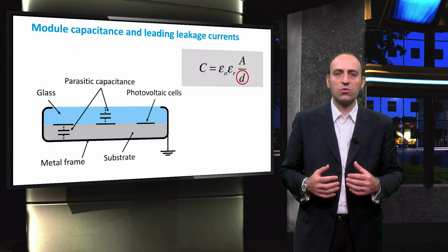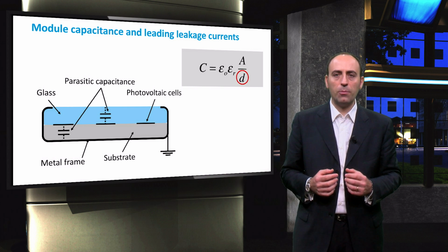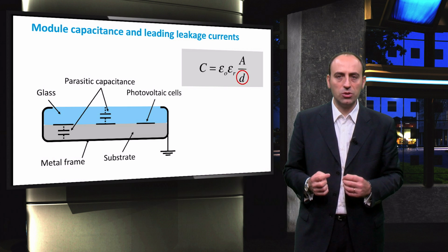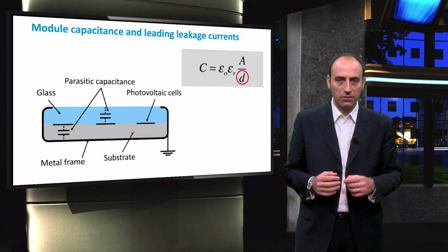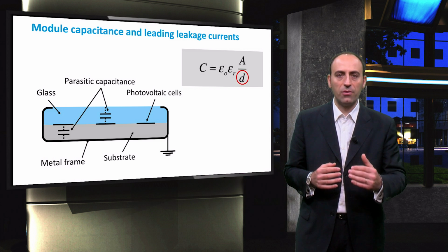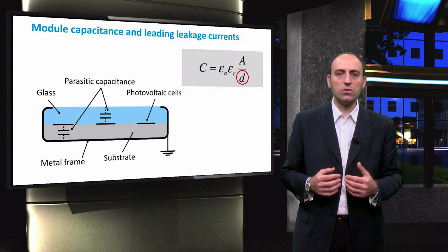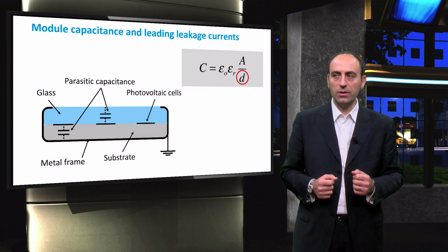As we saw when describing the overall configurations of the inverter, a transformer-less topology lacks the galvanic isolation between the PV array and the grid. In this way, the PV panels are directly connected to the grid, which means that there is a direct path for leakage ground currents caused by the fluctuations of the potential between the PV array and the grid.